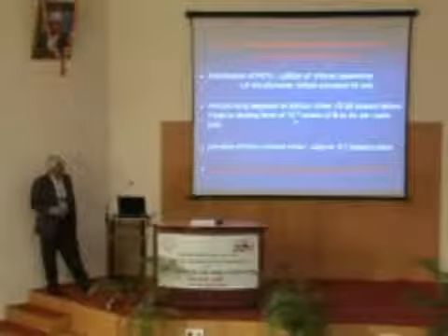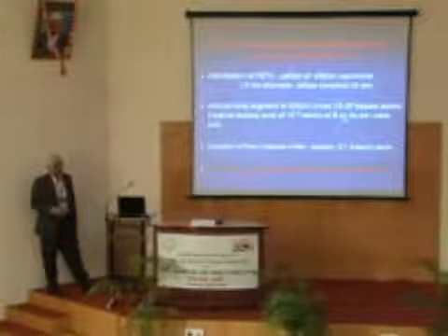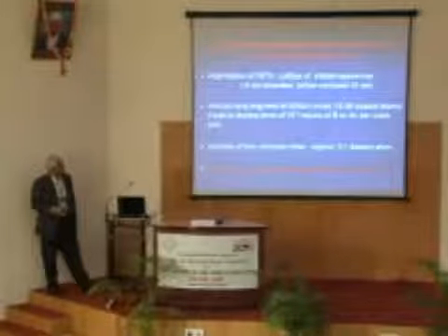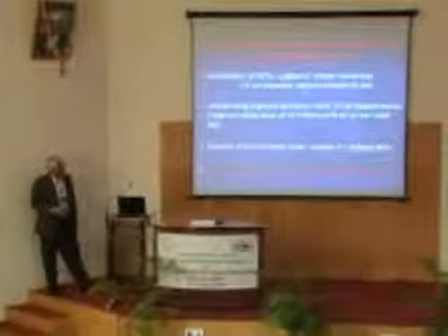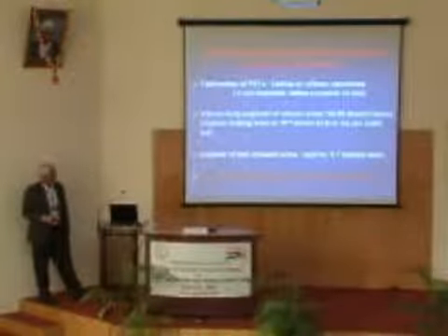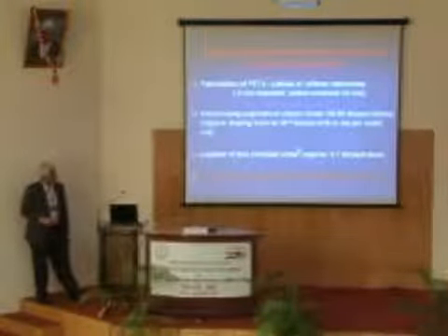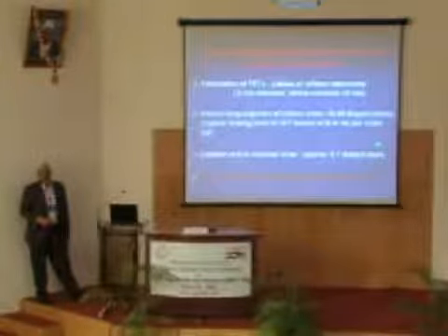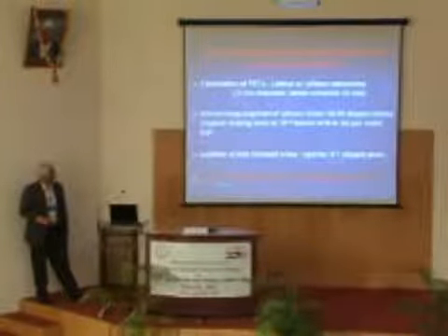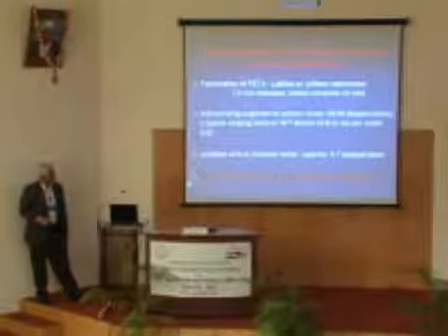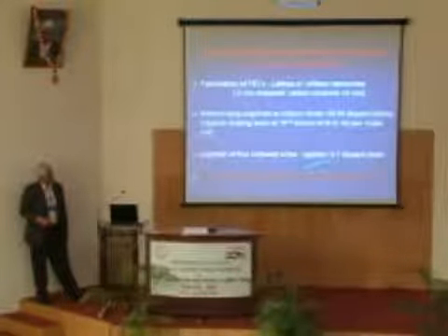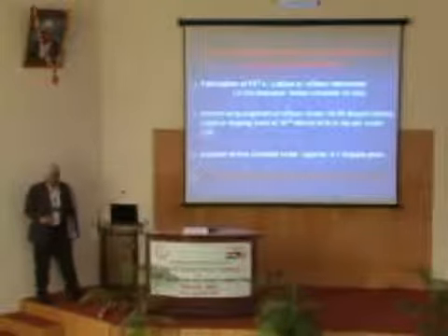If I use a typical doping level of bulk silicon, which is 10 to the power 18 atoms of either boron or arsenic per cubic centimeter, then for this lattice of silicon nanowires, which is micron long, I need about 15 to 20 dopant atoms. And if I make a junction of crossed wires for device purposes, we are looking at approximately 0.1 dopant atom. You see, approximations are breaking down because this is a non-statistical limit, and we are going to have unpredictable behavior of that particular device.